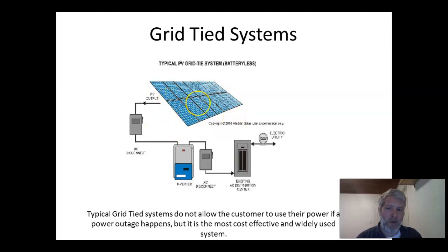Now we do have a regulation that residential systems can only go up to 600 volts, and so we're regulated due to the NEC at that. Most hardware can handle up to 1,000 volts, and there is some headway in different jurisdictions to get up to 1,000 volts, but mostly that's for commercial systems. And that's for your traditional DC optimizer system, which we'll get into later, and a string inverter system, which makes sense because they're in a string, they're in series with each other.